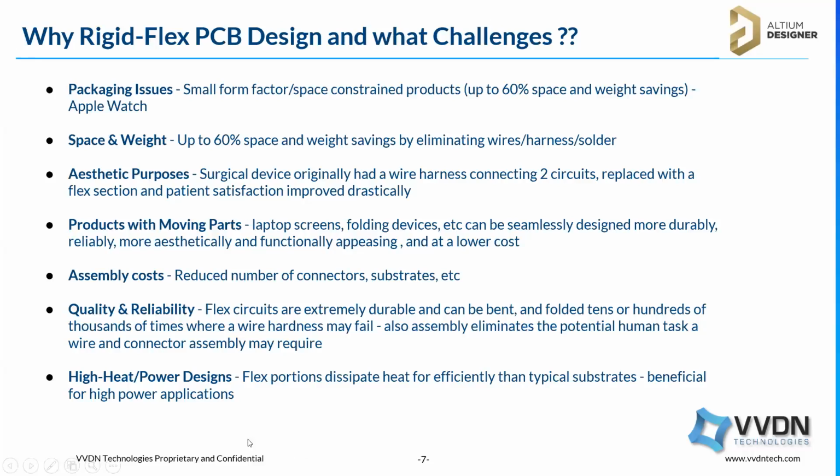Then products with moving parts, like a laptop screen or folding device. At that time also we can use this Rigid-Flex design, and it is simpler, helpful, more durable and reliable, and more functional also. And with low cost, we can develop our product. So assembly cost also reduces with this design. We can reduce the number of connectors and substrates also, so automatically assembly cost will reduce, and quality we can build also.